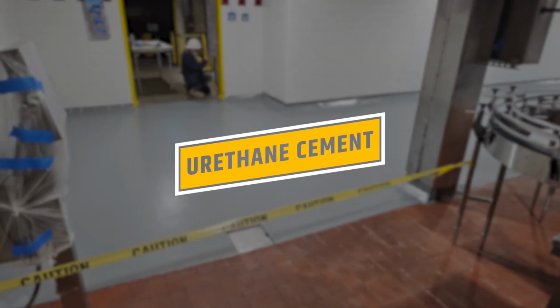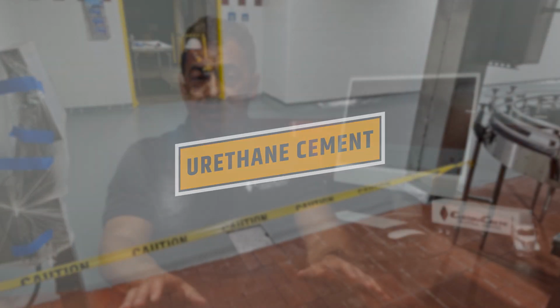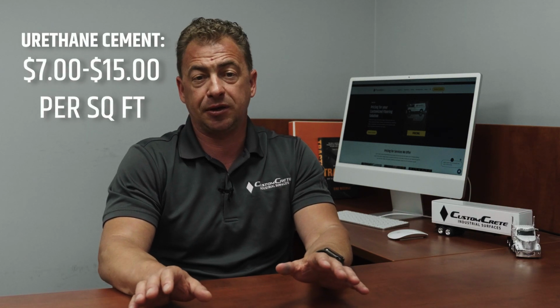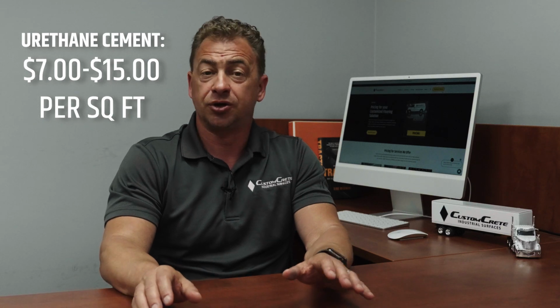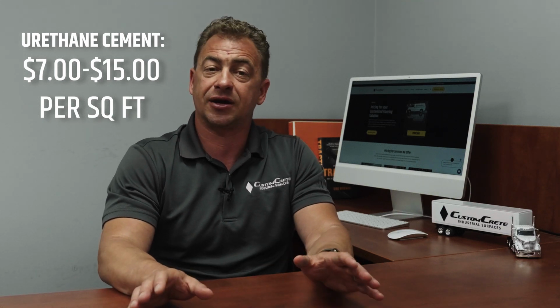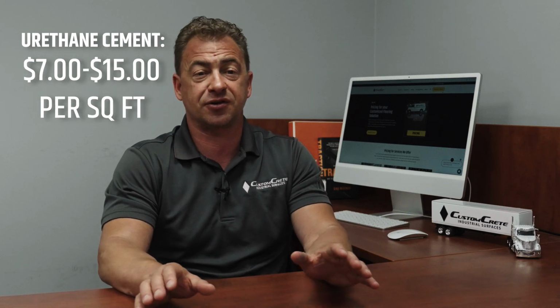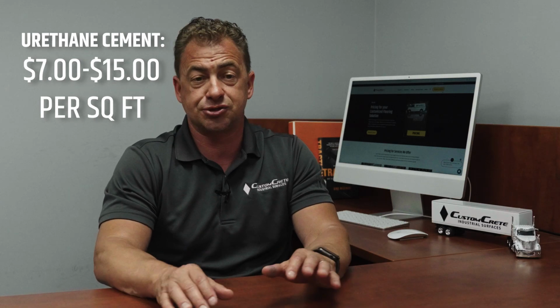Urethane cement. One of the best options for facilities is urethane cement. With a cost from $7 to $15 per square foot, this system is typically applied at a 1/4 inch thickness. Urethane cement is installed directly over a concrete slab, creating a seamless, durable surface that can stand up to harsh environments, frequent washdowns, and rapid temperature changes.